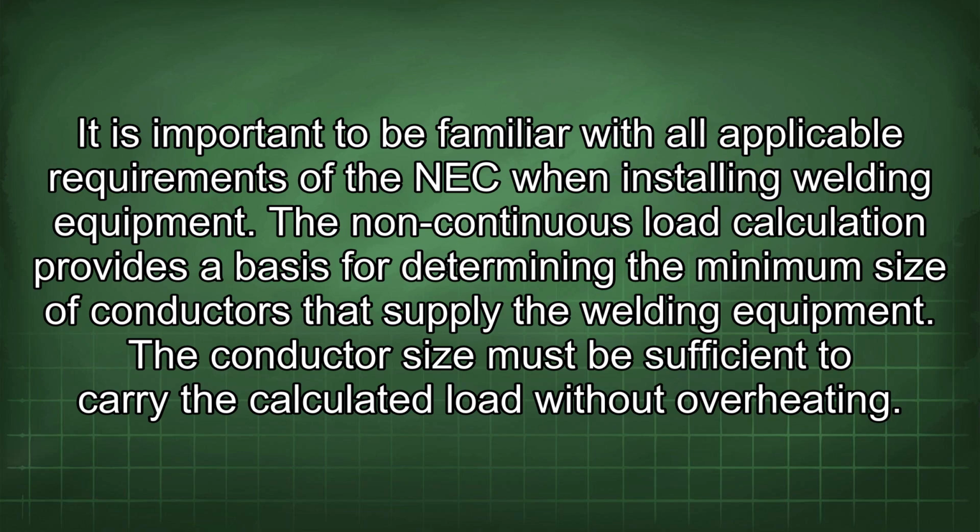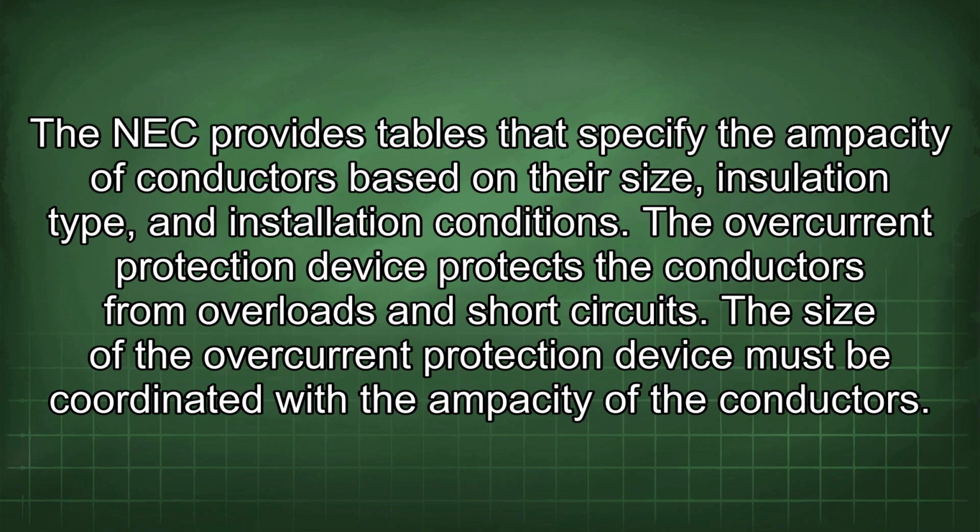The non-continuous load calculation provides a basis for determining the minimum size of conductors that supply the welding equipment. The conductor size must be sufficient to carry the calculated load without overheating. The NEC provides tables that specify the ampacity of conductors based on their size, insulation type, and installation conditions.